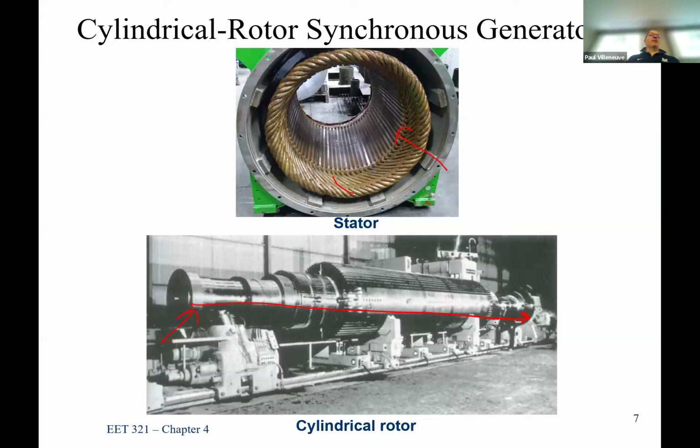Okay, so say more about that. You have more pressure. The rotor is pulling down more. You always have gravity pulling down. Remember, that has to spin, so you need a really beefy bearing. You'd have a lot of friction and you need a bearing that would be absolutely massive. So it just wouldn't be practical to have something like this.